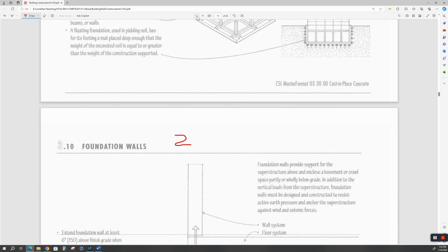Now, connecting your subfloor to your foundation walls. Where's that other nasty detail? Somebody had another nasty detail in here. Okay, all right. And there's several ways to do this. You can put a crib beam, a ledge on the foundation wall. You can put pockets in the wall. You can put a plate on top of the wall and use anchor bolts in there, and then you'll use steel plate anchors or hold downs on your fascia board that comes in on your joist.